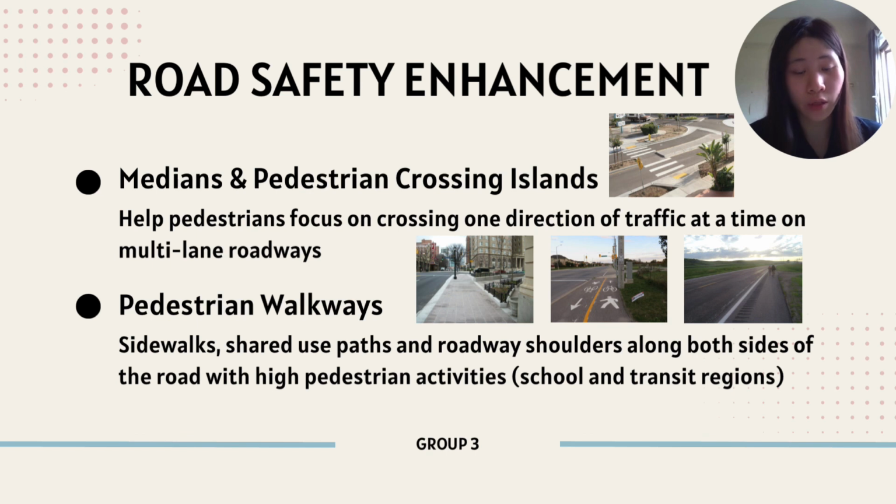Locating medians and pedestrian crossing islands between opposing traffic lanes enables pedestrians to focus on crossing one direction of traffic at a time, reducing the risk of accident. Pedestrian walkways should be provided in urban areas with high pedestrian activities, especially near school and transit regions.